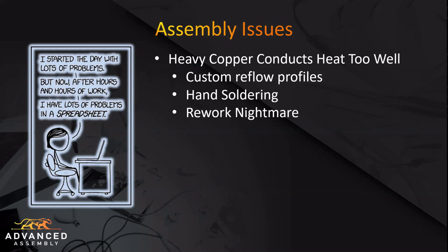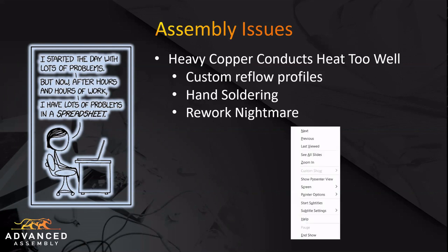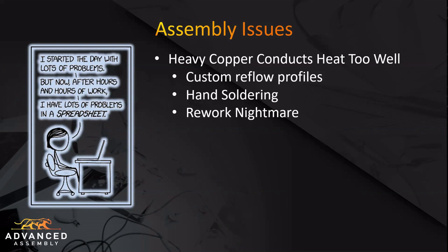Typically with a heavy copper and large layout board, there is a significant amount of preheat that is required, because ultimately what's going to happen with that is that you're going to have areas of cold solder if it's not done properly. So this all needs to be done through solder samples and your temperature profiling in your reflow oven.